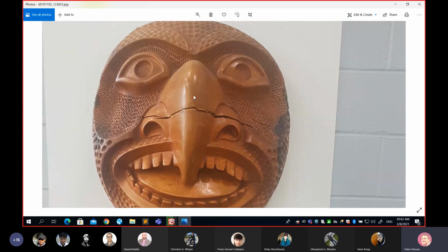You know, on the nose here, it's a very smooth surface, so we have no feature here. While every one of these small notches in the face is a feature point. A feature point is a point that is easy for a human to recognize as a very definite point, while on the nose there is nothing you can select. It's just a flat color. The feature comes from two things: whether there's an actual feature on the object itself, or there's a change of brightness. That's how the software will detect a feature.